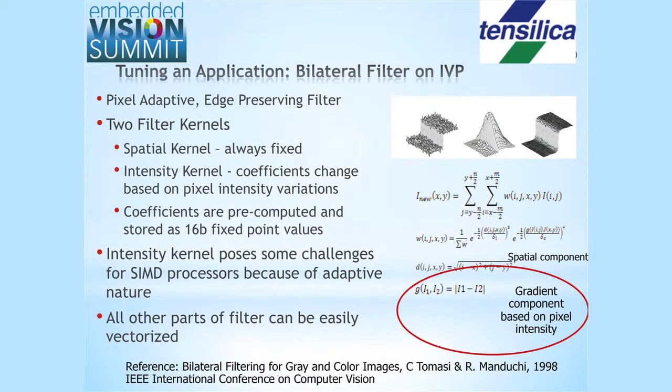So now let's look briefly at a medium complexity problem. Here we're looking at the optimization of a bilateral filter. A bilateral filter is kind of interesting in that it has some classic bulk processing characteristics like other Gaussian filter kinds of operations, which are essentially fixed coefficient. That is, the coefficients may depend on the distance, the location of a filter tap relative to the pixel output of interest, but doesn't really depend on anything else.